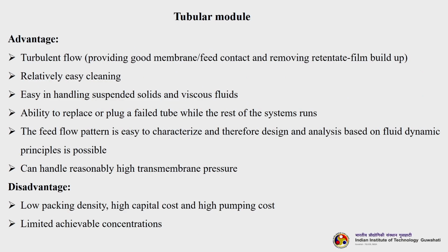The advantage of using this tubular module is the turbulent flow. Why is turbulent flow good? Because it provides good membrane and feed contact, which is very important. The entire feed that you are processing should come in contact with the entire membrane area supplied through a membrane module; only then will we get a separation, which is what we are targeting. Not only that, turbulence also helps in removing the retentate buildup.